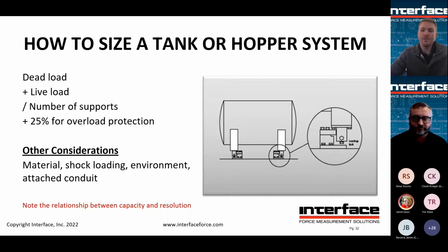One thing, I always tell you, let me give you as much capacity as I can while still providing the resolution that you need, or get as close to it as you can. And the resolution is defined as the smallest change in mechanical input which provides a detectable change in the output signal. So what are you reading by? Is it going to be a 1%, a 1 pound increment, 5 pounds, 10 pounds? What is good enough for the customer?